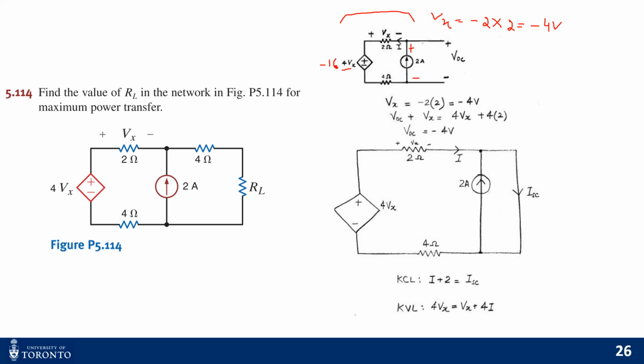Now, what is the voltage drop across the 4 ohms resistance at the bottom? Since the current flows in the anticlockwise direction, the voltage polarity will be plus here, minus here, right? And the voltage drop across it will be 8 volt, right? So we see that we know all the voltages across all the circuit elements, right? Except the VOC. So if we apply KVL,